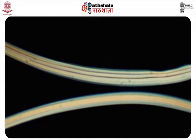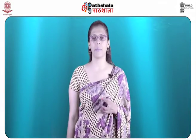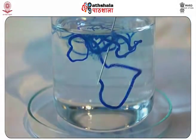Synthetic fibers. Rayon is a manufactured regenerated cellulose fiber. It is made from purified cellulose, primarily from wood pulp, which is chemically converted into a soluble compound. It is then dissolved and forced through a spinneret to produce filaments, which are chemically solidified, resulting in synthetic fibers of nearly pure cellulose. Because rayon is manufactured from naturally occurring polymers, it is considered a semi-synthetic fiber. Specific types of rayon include viscose, modal and lyocell, each of which differs in manufacturing process and properties of the finished product.